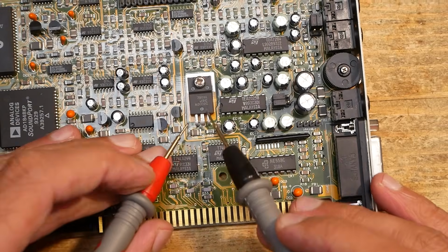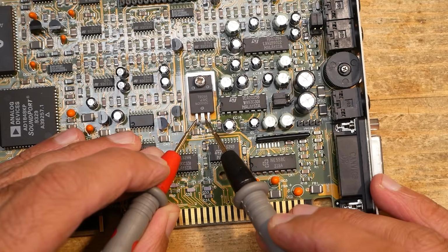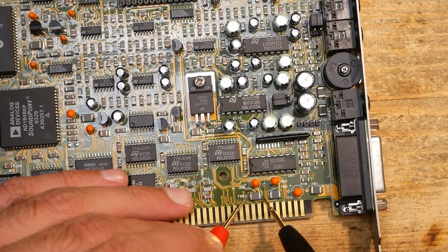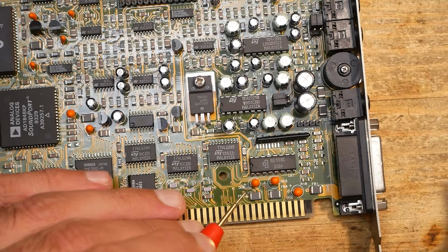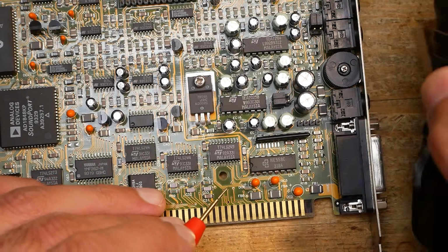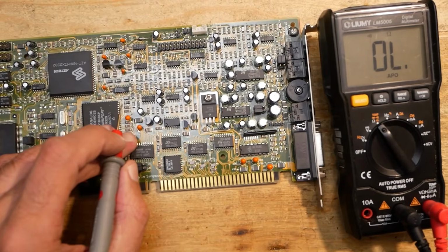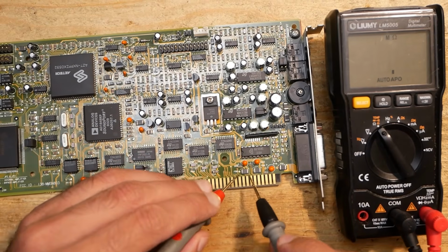These cards seem to have a common issue, so should you get your hands on one of those, check out the rails. Yeah, and as last time, also here we most probably have a shorted capacitor. And the ferrite bead has no continuity, exactly like in the case with the Basic 16. So on these cards I'll have to change the capacitor and the ferrite bead, then hopefully we will get a working card.